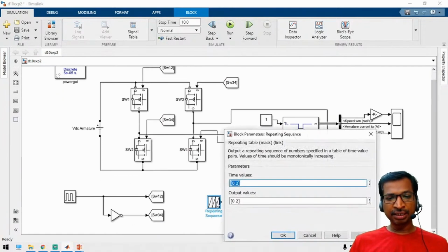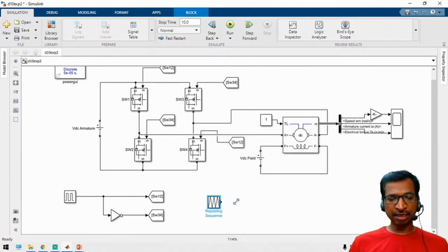And let us take the triangular waveform from 0 to 1, right? 0, 0.5 and then 1. And then frequency 1 divided by 1000, 1 kilohertz. And then values 0, 1, 0. So now we can get a triangular waveform.